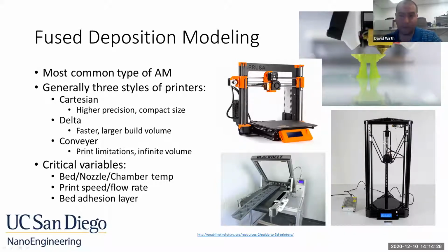And the last thing, probably the most challenging part of 3D printing, just for anyone, is bed adhesion, right? Getting the prints to stick to the bed throughout the print is very challenging. Generally, you want a bed with a PEI adhesion layer. These Prusas are, the reason everyone gets these Prusas is because they have a very good bed adhesion layer and they have a computer controlled auto leveling. Something like this Delta is going to be very hard to level because the bed leveling is harder because you have a kind of a hemispherical effect from this Delta geometry.